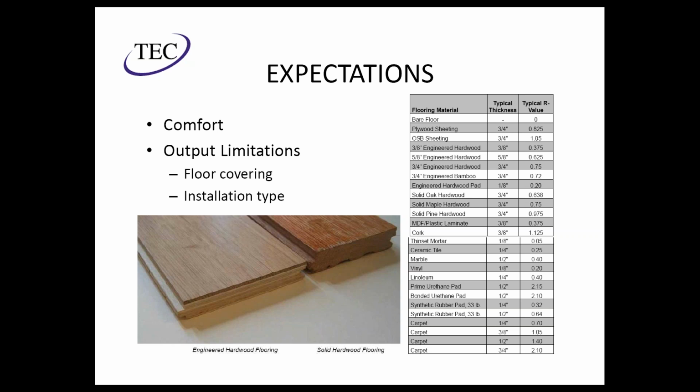So you have to be a little more careful with those. I'm sorry, vinyl should not be in that group. Carpet is definitely a bigger insulator. If you're going with vinyl or tile or marble, those are traditionally much better radiant materials because they allow heat to pass through them and they can hold heat over time.